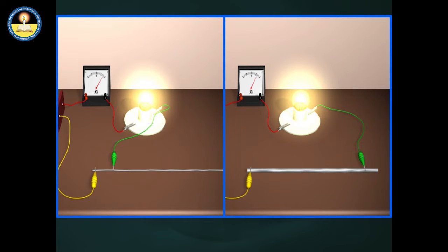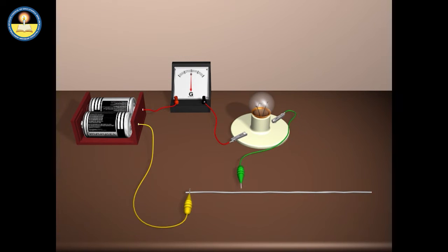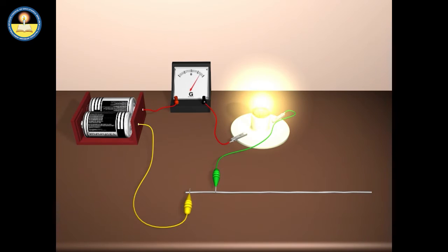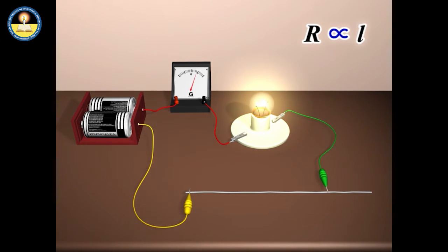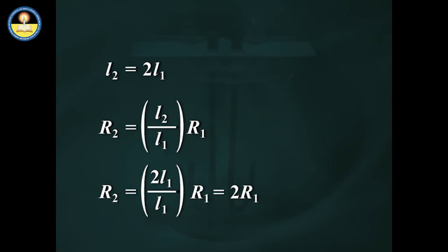Using the Ohm's law, expression for the heat produced by a conductor can be modified as shown. For more understanding, let us try some numerical problems. An immersion water heater of resistance 500 ohm is connected to the main supply of 220 volt. Measure the heat produced in 30 minutes.